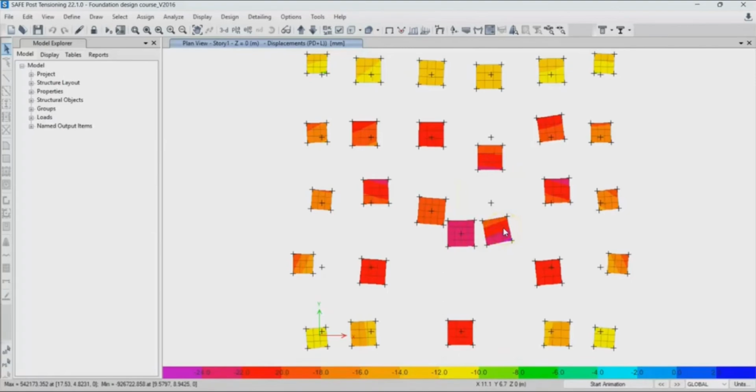Which is going to make them settle as a single unit, right? So if you introduce a tie beam that ties this footing to this footing, then they are going to settle as a single unit, which will eliminate the differential settlement. So you are basically going to introduce a stiff, heavily reinforced concrete strap beam, or we can say tie beam, that is going to directly connect the isolated footing pads at the foundation level.